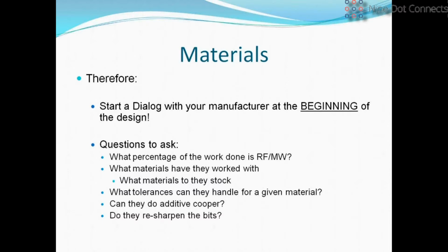Lastly, are they resharpening the bits? If you're going to do RF design or anything with high precision, you want them to use a new bit every time they spin one. A lot of these companies, to save money, will try to sharpen it. On some of the slower designs, yeah, fine, they can reuse it. But keep in mind that anytime you sharpen something, you're removing material, and there's no guarantee that the symmetry is going to be the same as when the original bit was created. So it's best that you have them not reuse a bit, and use a new bit every time. And if that's an additive cost, so be it. At least that helps with your yield.